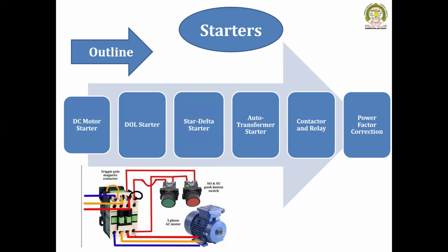To avoid damage to the distribution network or to the motor itself, it is necessary to use starters. So a starter is a sort of protection device used for the motor against the inrush value of current.